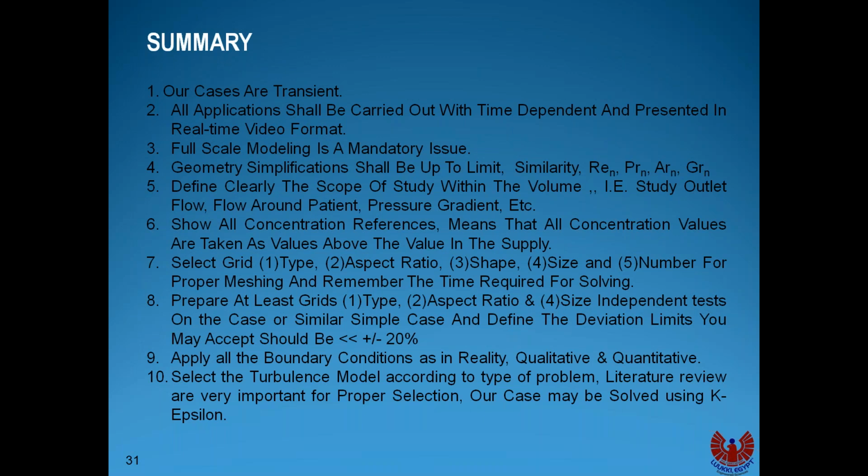In our case, our thresholds in the isolating rooms will be the thermal comfort conditions, the number of air changes, the cleanness, I mean, the noise, the temperature, the relative humidity, all this together. But at the same time, all this together shall be controlled to avoid any generation of the viruses or fungus. So we are talking about thermal conditions and indoor air quality.